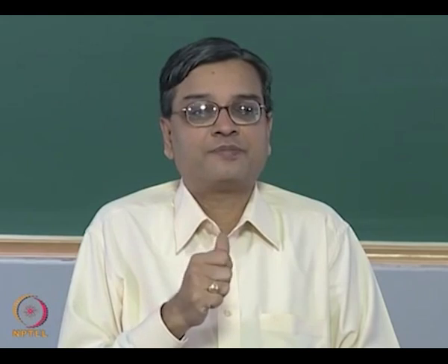And in this class what we had looked at was, we evaluated the stress intensity factor by using the stress function definition, and then we proceeded to find the stress intensity factor for triangular loading on the crack faces. Another important problem is a constant pressure on the crack faces, which is an equally important practical problem, and we found the stress intensity factor as P naught root pi a.